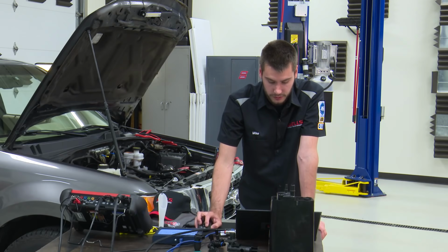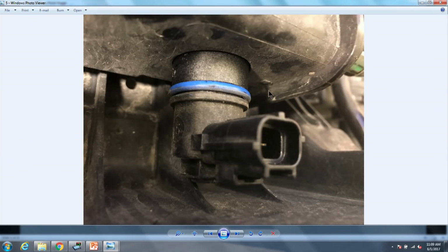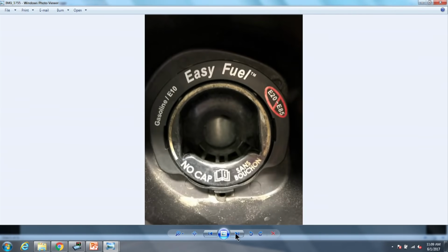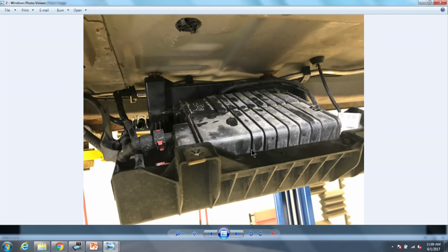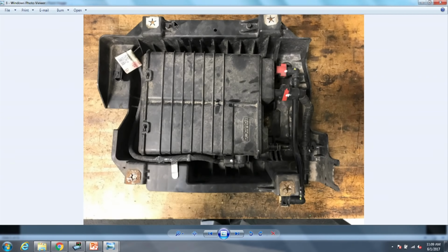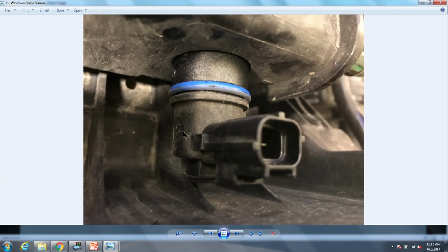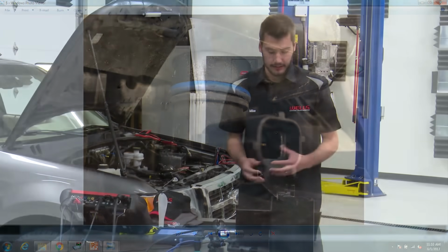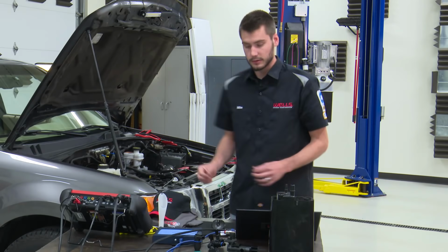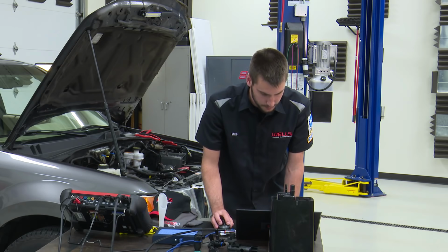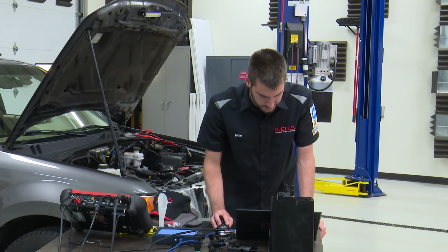Now, of course, you're not able to pull the vent off with this black plastic shield around here. You would have to remove the canister from this black plastic shielding. There's just some bolts holding it on the bottom in order to get the vent solenoid out. But that is where it goes, right on the canister. So it's kind of a unique vent design on this vehicle. So just wanted to bring that up because we're going to be playing around with that in a little bit.